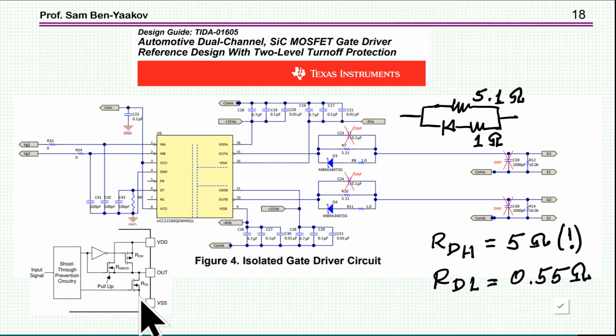Here it is an N channel, which is of course easy because it's referred to ground and you can generate a voltage which is higher than the ground. But here it has a P channel, which is kind of limited in the current. So therefore they have another N channel, which as you can see operates only halfway, doesn't have a high side drive. Okay, so it's only starting at the beginning and then it's not functioning as the voltage goes up.